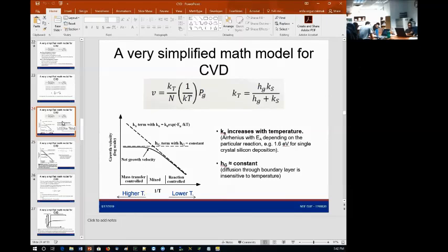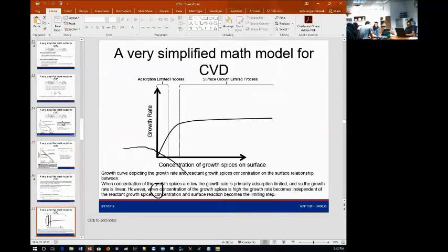We have seen that, logarithmic scale of growth, with respect to 1 over temperature. The other one is this one. So we are adsorption limited here. They offer more silane, and it does go into reaction easily and nicely. We offer more, but it gets saturated because it becomes surface growth limited or chemistry limited on the surface. So we have established these two.